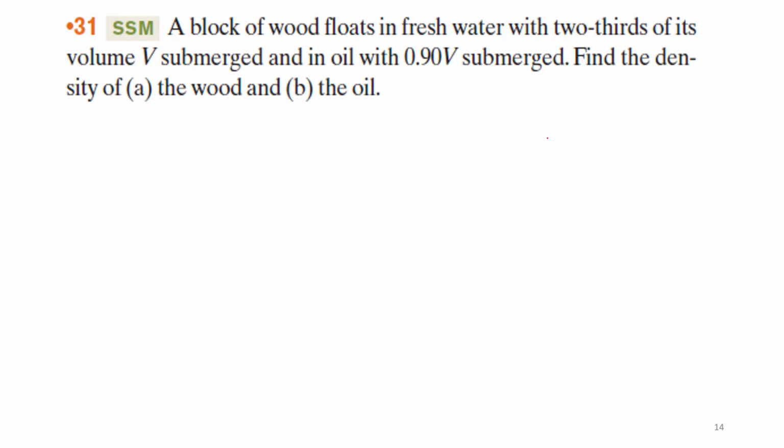So as we said, floating, buoyant force is equal to gravitational force. Okay. So you simplify by g because buoyant force is mf g, this is m g, so basically you get mf is equal to m. So what is mf? That is the mass of the fluid displaced. Okay, so mf will be rho f vf, the volume of the fluid which is displaced, which is equal to the mass of the object, basically. The mass of the object will be rho v. Okay.